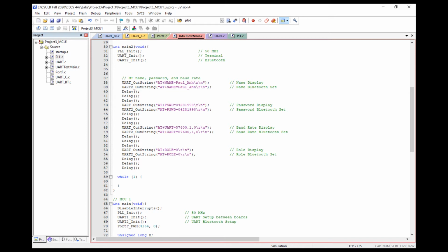This file also contained a second main method. In this method, we show a message for the user to choose between sending information to the speaker or onboard blue LED. With this message, the user is expected to send an F or B, followed by a baud rate. If the parameters are out of bounds, the user is asked to re-enter the input.